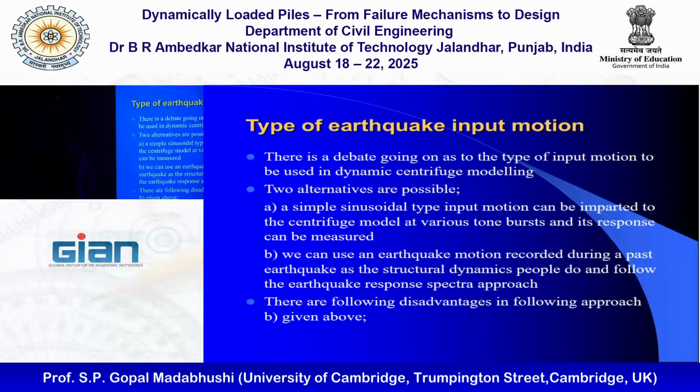If you put, say, something like the El Centro earthquake or Kobe motion, then that has quite a lot of different frequency components and the amplitude is constantly changing. I'll show some traces to you. Then can we still interpret what's going on in our soil? Well, his argument is you can't, because everything is changing, so it'll be like garbage in and garbage out.